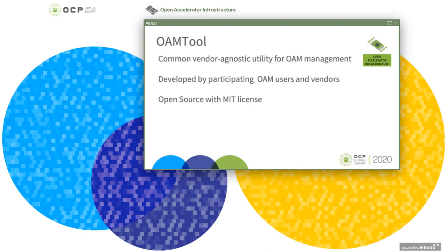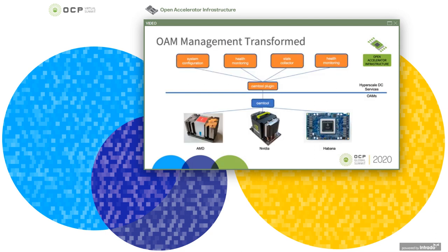I want to mention that it is not uncommon to develop a vendor-agnostic tool to manage hardware modules from different vendors. Consider the ethtool to manage the different NICs in the network world, or consider the NVMe CLIs to manage the SSDs in the flash world. With a common tool, the management of the OAMs in the DC will be greatly simplified. Our tooling team now only needs to develop one plugin to manage all the OAMs because all the functionalities will go through this common tool.